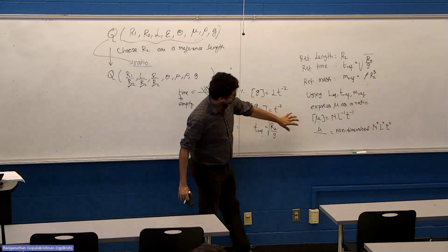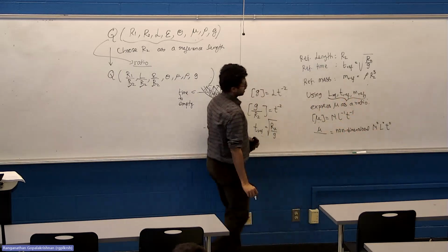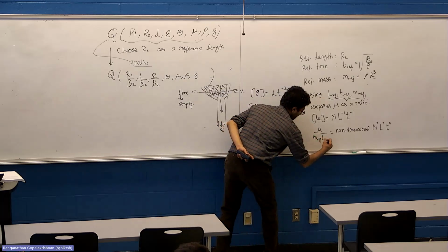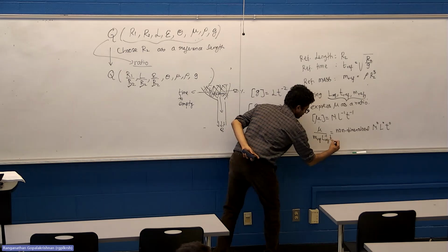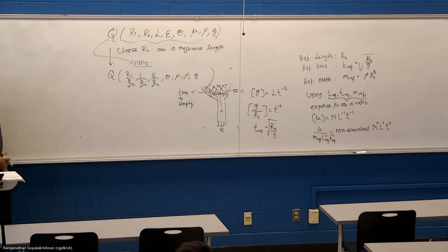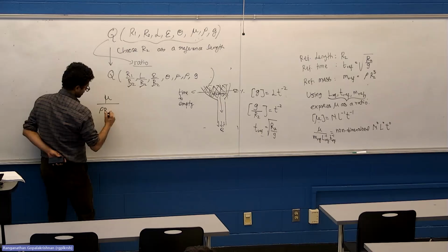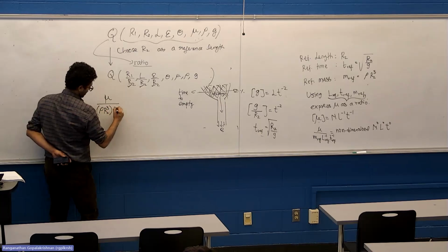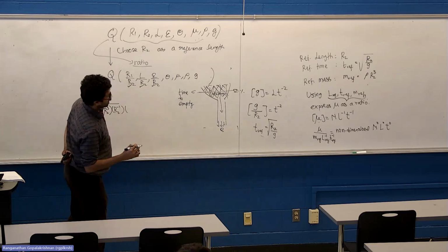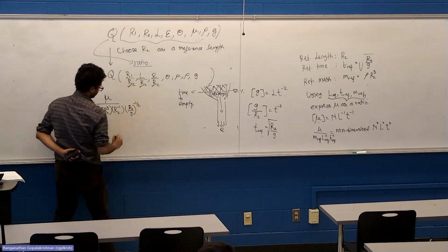I should be taking M ref, multiplying it with L ref inverse and T ref inverse, and that should non-dimensionalize viscosity. What is that quantity? Viscosity divided by rho R2 cube, divided by R2, divided by what is time? R2 over G to the minus one half.